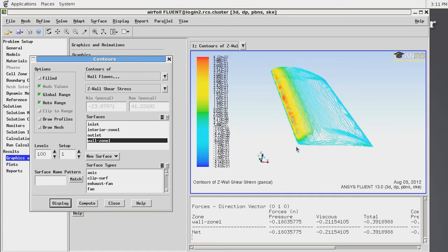And the difference between large eddy simulation and the RANS method simulation is huge. In the large eddy simulation, it's not a time average method, so you would see a live simulation during time. As for the RANS method, it is a time average method where at some point, even if you set it as a steady or unsteady case, the velocities in the streamlines will get averaged and become constant, and that's not what we want.